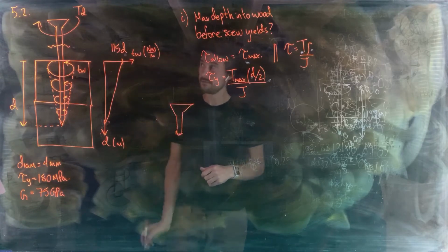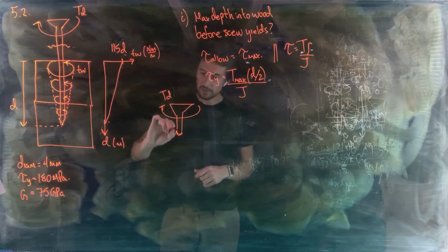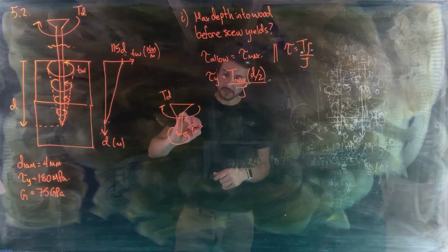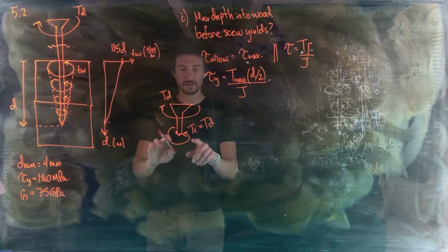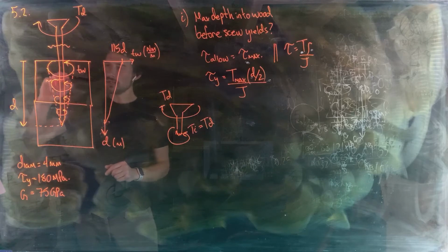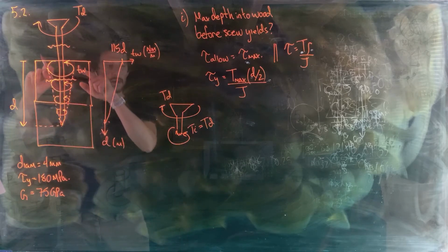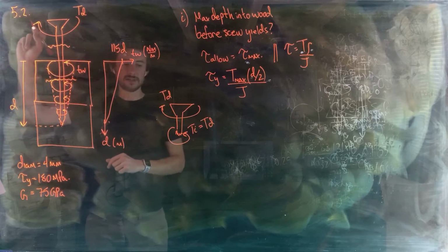there we go, there's our free body diagram. We've got T_D like this, and our internal torque is going to be equal to T_D because the sum of the torques needs to be equal to 0. So internal torque equals T_D. If we make a section cut any lower than that, we're going to have a little bit of the distributed torque in the diagram, and it's going in the opposite direction as T_D.